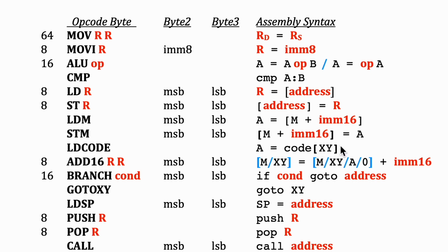That's because we presumably know what bytes are in the flash memory, and if we want to grab a particular byte from the flash memory, instead of providing a 16-bit address, it makes more sense to just use a move immediate instruction and provide the actual byte itself.